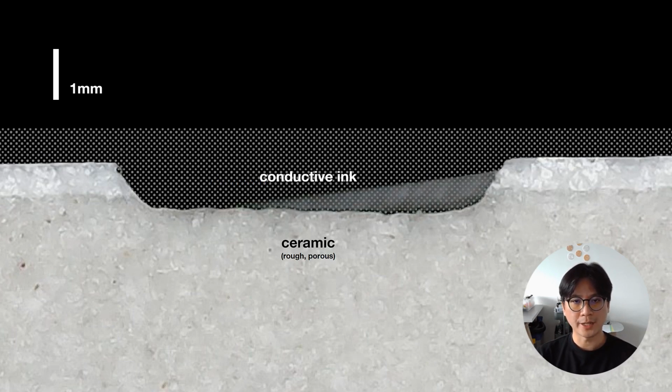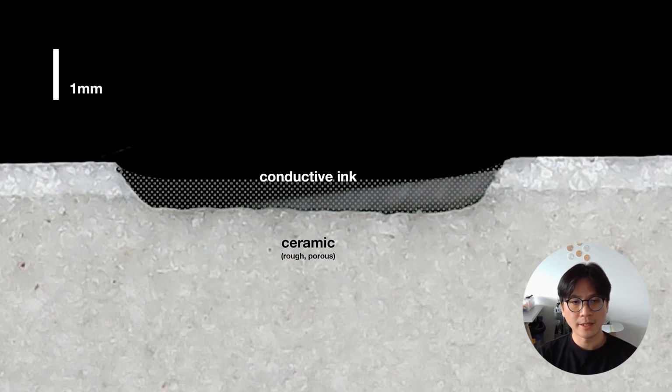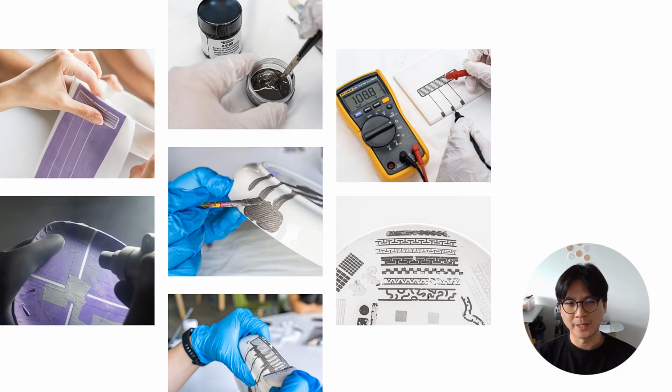Essentially, we could apply conductive ink to the surface of a resist blasted object and remove excess ink from the smooth glazed surface. Ink will remain on the rough and inlaid traces created by sandblasting, and therefore such a process would enable us to define and incorporate complicated circuit patterns onto the surface of ceramic objects. As with all material explorations, adapting resist blasting to circuit fabrication was not a straightforward process, and do refer to our paper for a lot more details of this process. For now, let me walk through the circuit fabrication approach we developed with a short video.